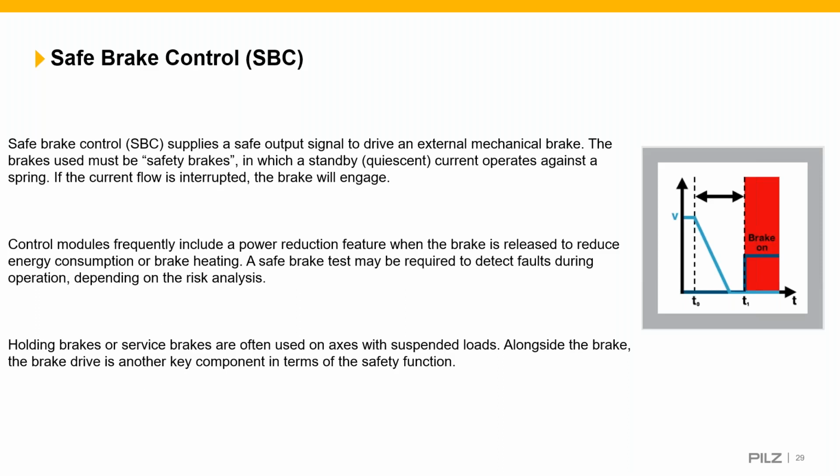So safe brake control, and again, this is one that gets overlooked in terms of it might be used, but certainly the fundamentals that need to be adhered to are not. So safe brake control, SBC, supplies a safe output signal to drive an external mechanical brake. The brakes used must be safety brakes in which a standby current operates against a spring.